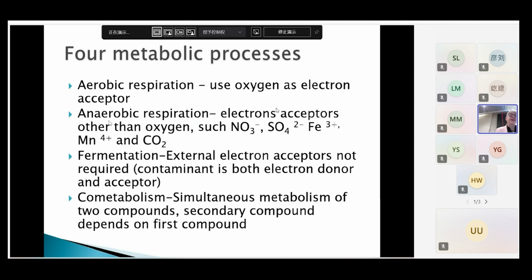Yeah, so all of the chemical analysis done for metals, gas chromatography, things like this, total organic carbon. There are a lot of techniques that are available now, FTIR for certain bands, gas chromatography with mass spec, ICP-MS for heavy metals, atomic absorption for heavy metals. There are all sorts of techniques, and of course you have new contaminants that have been identified, like PFASs and things like this, as new contaminants of concern.